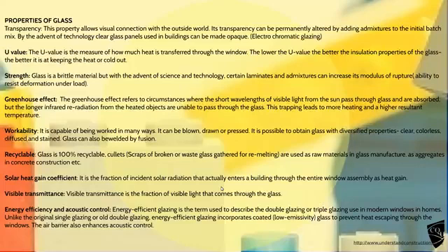Solar heat gain, that's the fraction of the solar radiation that enters the building. Basic glass allows most of it to go straight through. You can put reflective films on, you can put a molecule or 2 thick metal film over them. I used to use silver quite often. When you've got double and triple glazed windows, then you may have a coating on the internal sheet of glass where it can't get damaged.